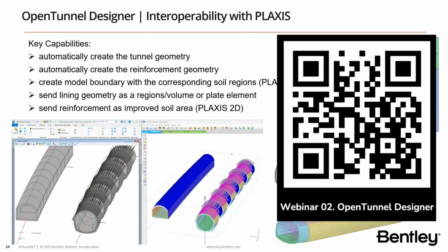Giacomo is asking, can you assign property sets to model elements? You can assign them through item types technology. Basically, the item types are property sets that are attached to the feature definition. Those item types can read the properties of the solid and the civil properties, like the length of the bar, the diameter, the element it belongs to.